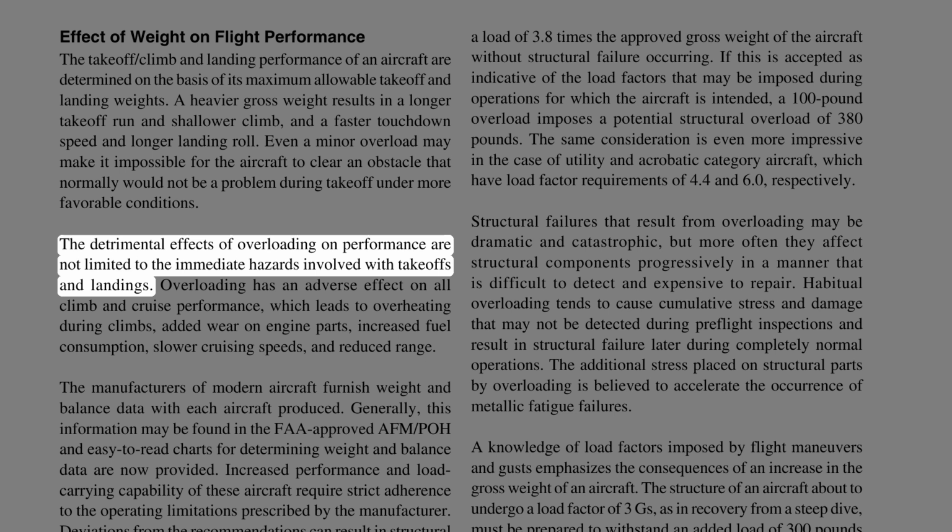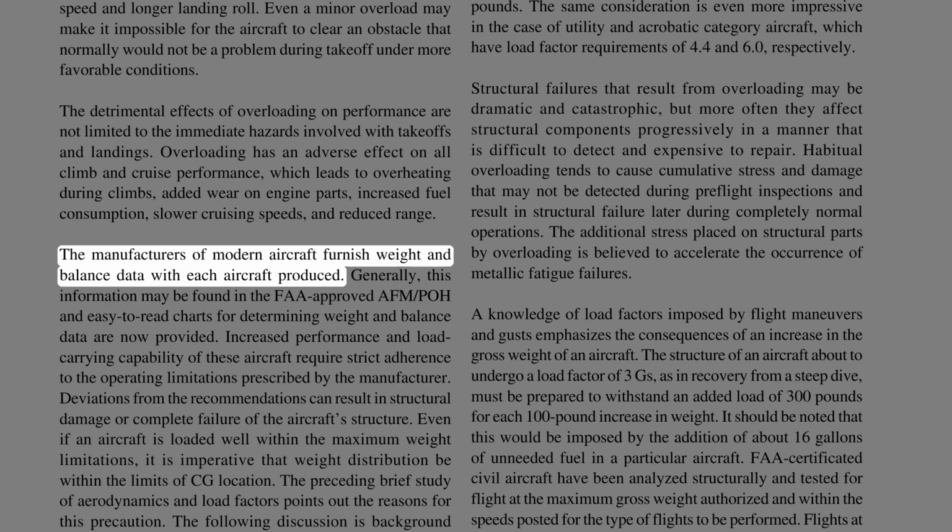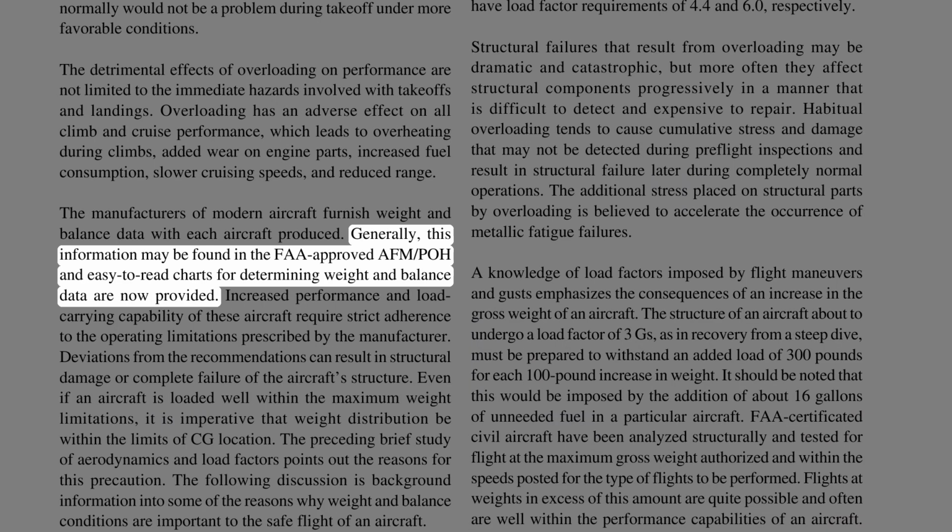The detrimental effects of overloading on performance are not limited to the immediate hazards involved with takeoffs and landings. Overloading has an adverse effect on all climb and cruise performance, which leads to overheating during climbs, added wear on engine parts, increased fuel consumption, slower cruising speeds, and reduced range. The manufacturers of modern aircraft furnish weight and balance data with each aircraft produced. Generally, this information may be found in the FAA-approved AFM, POH, and easy-to-read charts for determining weight and balance data are now provided.